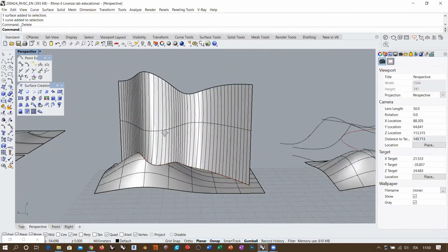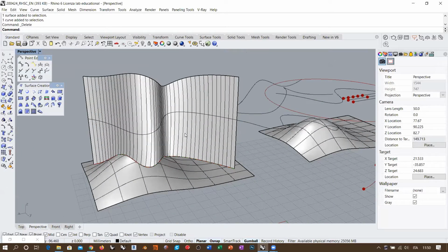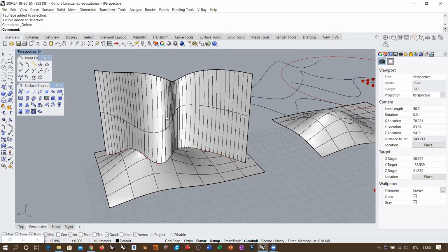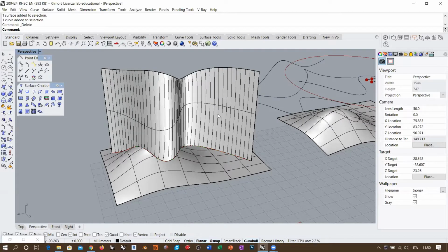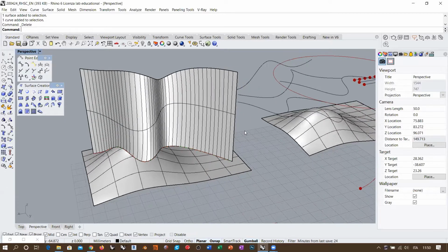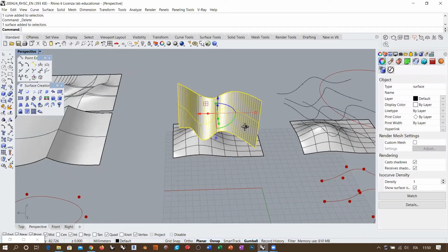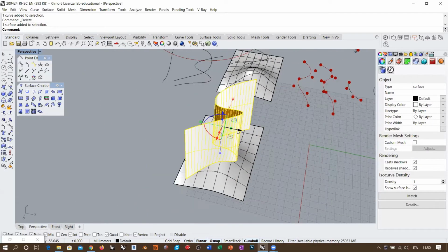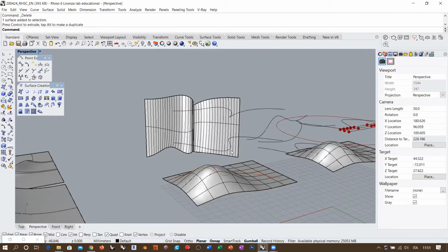But anyway, this is something that you might want to take into consideration, because the precision of the cross section can be adjusted, or the rebuild of the cross section can be performed outside of the loft and inside of the loft as well. The only difference is that you don't have control over the maximum deviation, which is an important parameter. Another consideration is that this is the rebuilt loft. So this is a possibility you have.